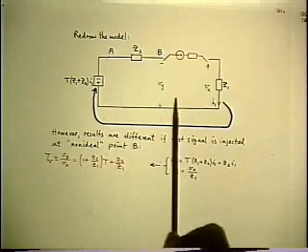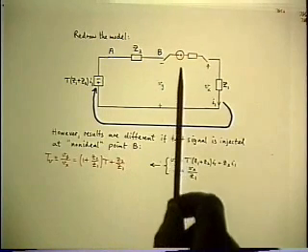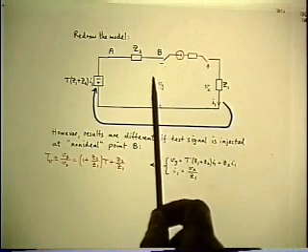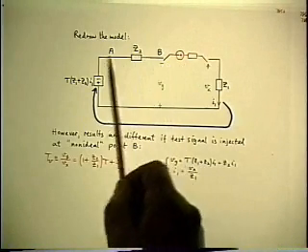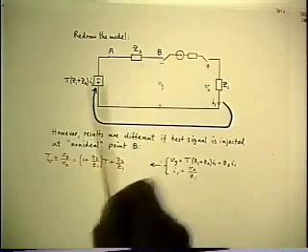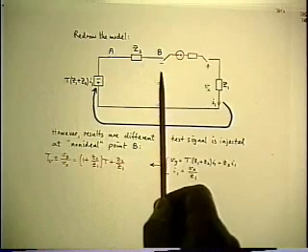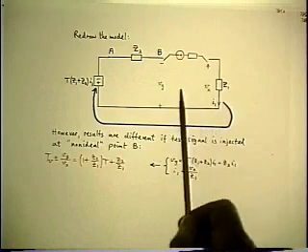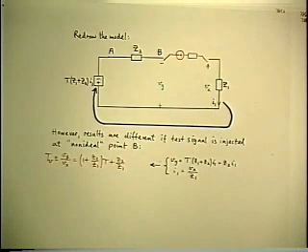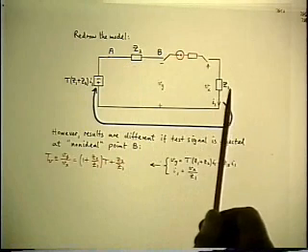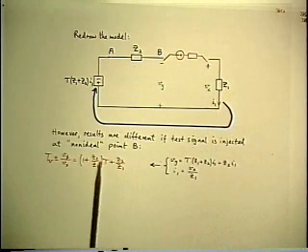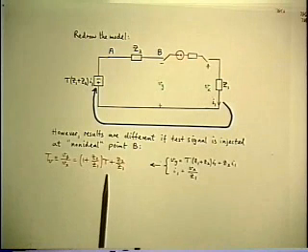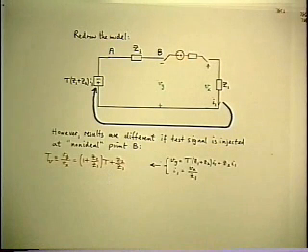which the interpretation of that is, when you're searching for an injection point, what you have to check is the ratio of the output impedance of the source looking back into the loop from the injection point to the impedance looking into the loop the other way. It's the ratio of Z2 to Z1 that matters. If it is small enough, the measurement of Vy over Vx will be close to the true value of T.